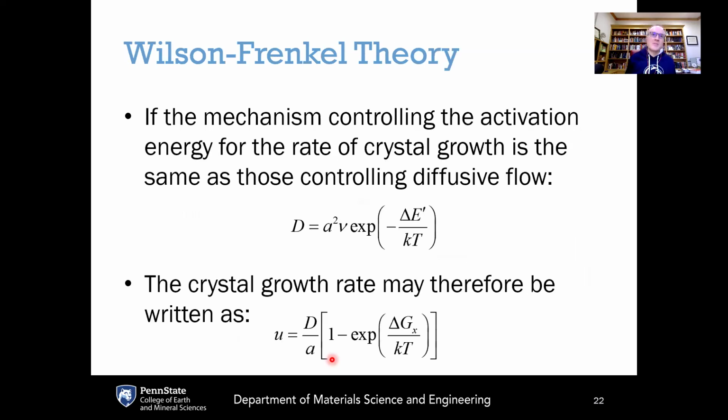Now, there is a modification to this theory that was developed by Turnbull and Cohen that was subsequently taken further by Wilson-Frenkel. Wilson-Frenkel theory then relates the kinetics of this process to another kinetic property, which would be the diffusivity D. And the assumption with Wilson-Frenkel theory is that the atomic mechanism that governs the crystal growth rate is the same as the atomic mechanism governing diffusivity.